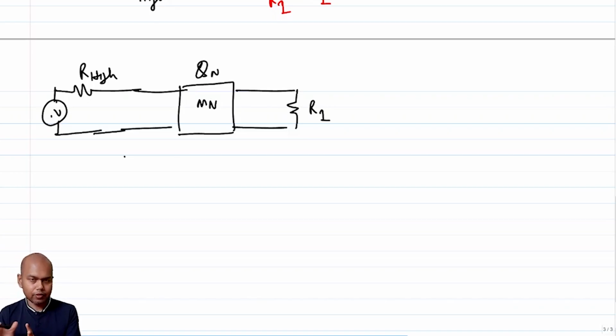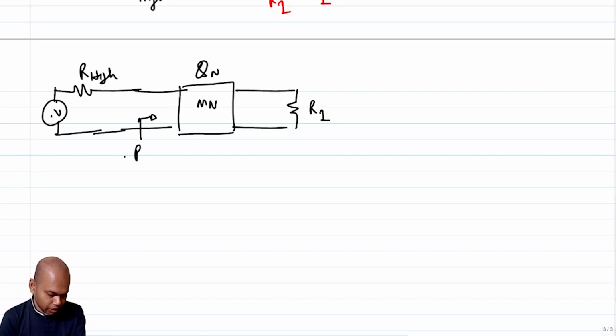While finding the Q factor of the network, we are assuming that the entire power, the lossy part of the power, is the one that is dissipated in the load, right? So that's the dominant one. So that's why we are neglecting the power loss in the matching network while we are trying to find out the Q factor of the network.